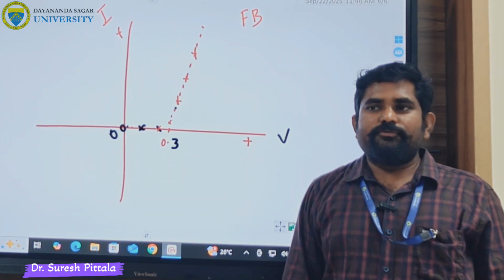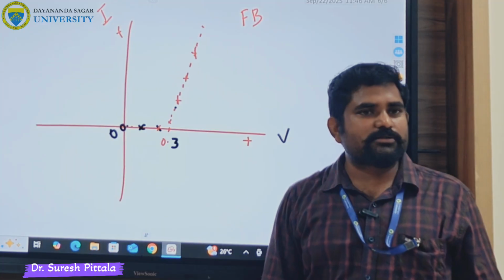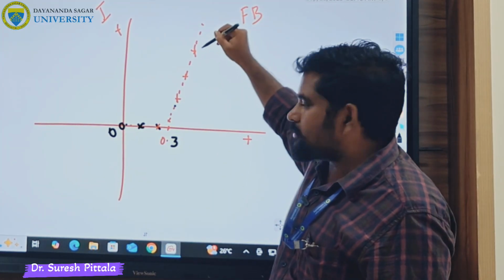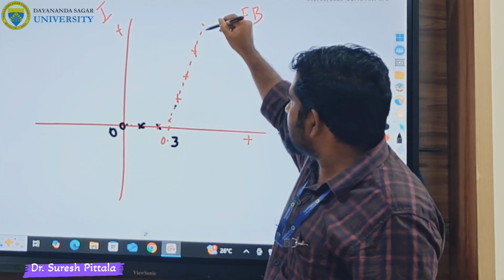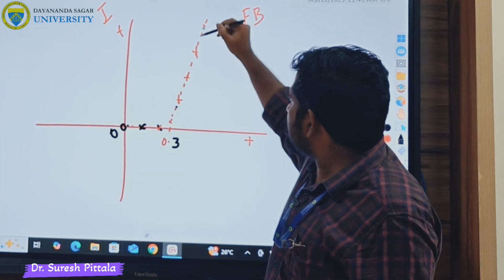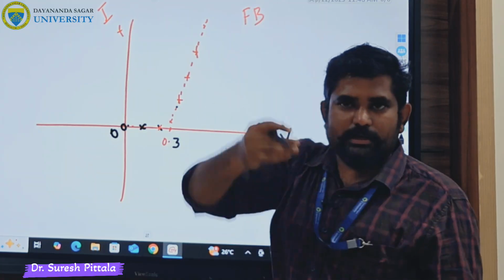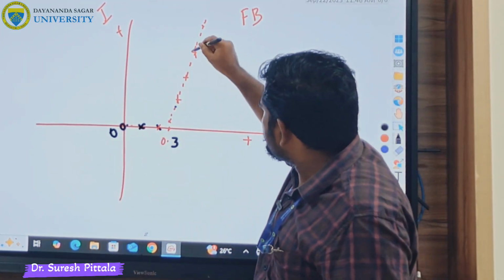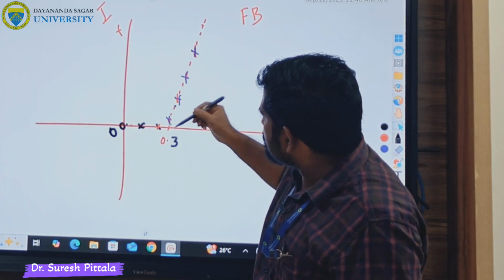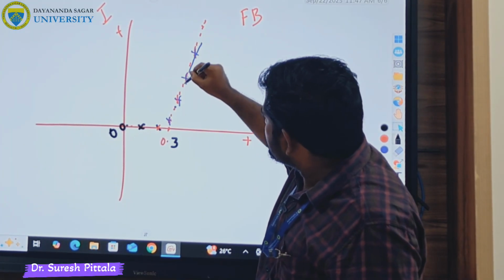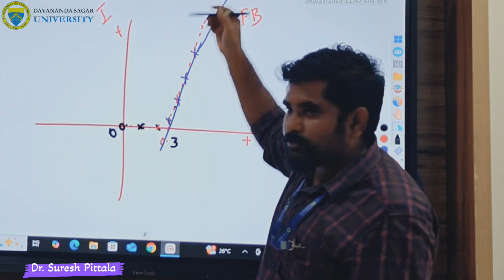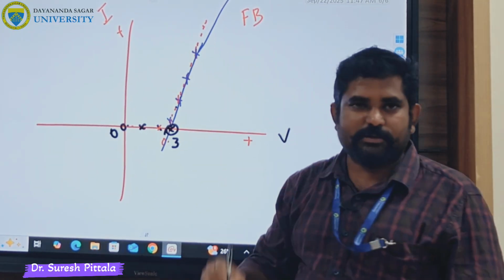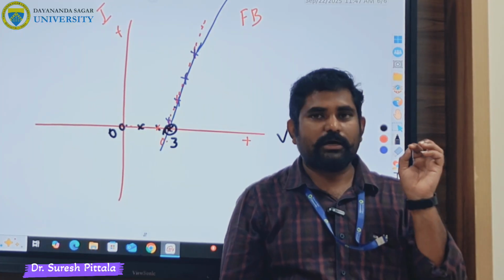Now in the aim, you did not say, we also want to find out what the knee voltage is. Knee voltage is the operating voltage. To find it, you take a straight line and extrapolate it to the origin, because we don't have points there. Where we have points, I draw a line connecting all these points. This is extrapolation, right? Extrapolate to the x-axis. Wherever it touches the x-axis after extrapolation, that is called knee voltage or threshold voltage in the forward bias.